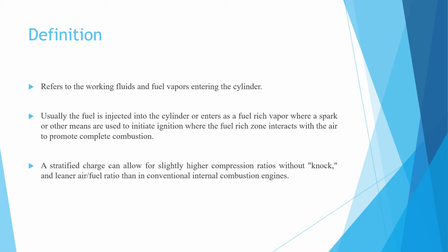So students, the stratified charged engine refers to the working fluids and fuel vapor entering the cylinder. Usually the fuel is injected into the cylinder or entered as a fuel rich vapor, where a spark or other means are used to initiate ignition, where the fuel rich zone interacts with the air to promote complete combustion.